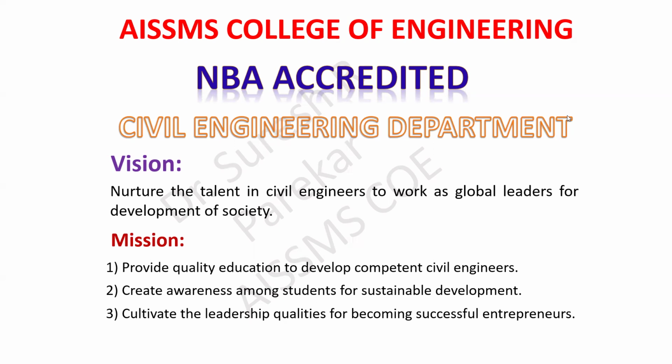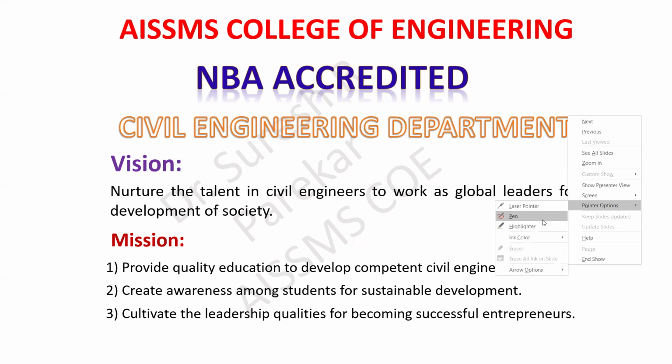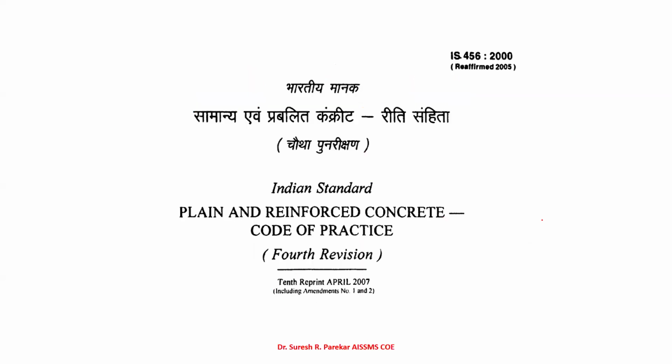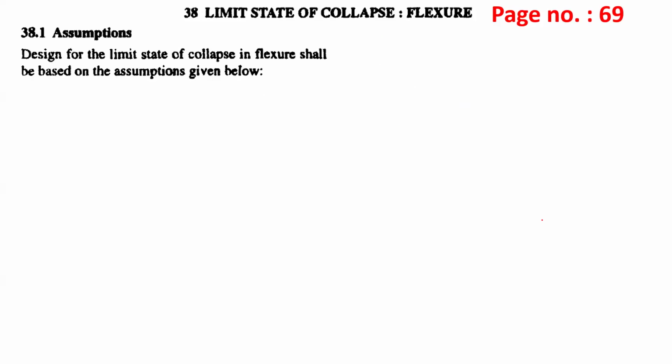Good evening. Now we have the next video, which again continues with the clauses of IS 456, plain and reinforced concrete code of practice. We have seen that we mainly have two limit states. One is the limit state of collapse, which is in flexure, and the other is the limit state of serviceability. Here we will see the limit state of collapse.